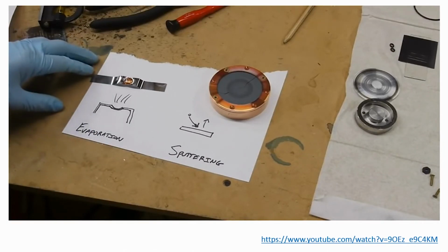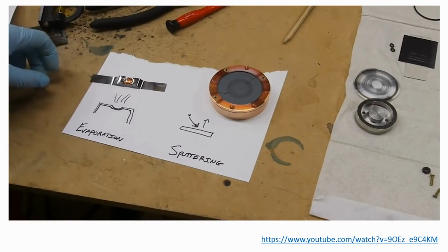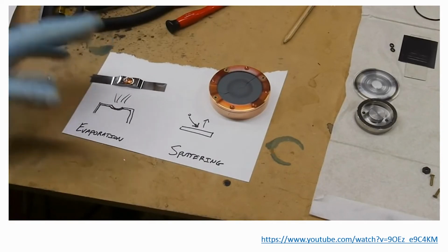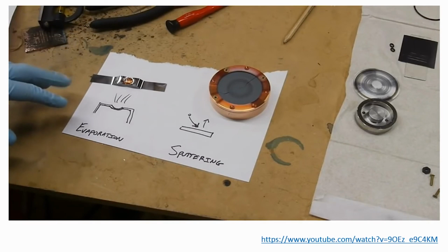So if your material can't take it for whatever reason, or if it changes into another material at that temperature, then this isn't going to work. And when we're talking about making conductive ITO coatings, this is definitely the case, where if you heat ITO up in a vacuum, as far as I know, it reduces itself back down to base metals, and it doesn't work.